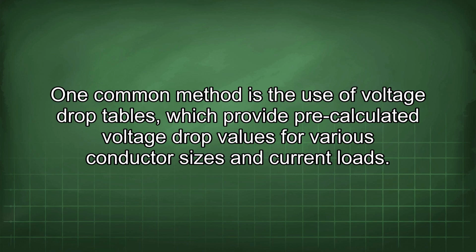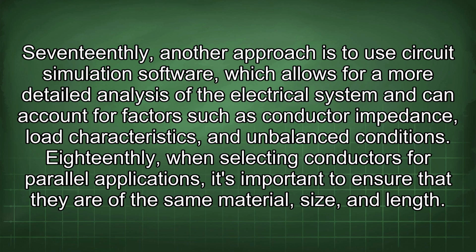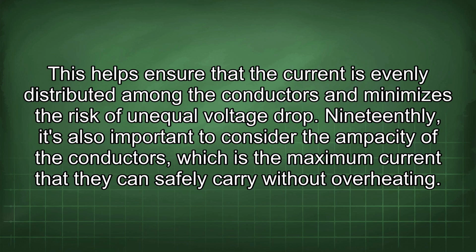17thly, another approach is to use circuit simulation software, which allows for a more detailed analysis of the electrical system and can account for factors such as conductor impedance, load characteristics, and imbalance conditions. 18thly, when selecting conductors for parallel applications, it's important to ensure that they are of the same material, size, and length. This helps ensure that the current is evenly distributed among the conductors and minimizes the risk of unequal voltage